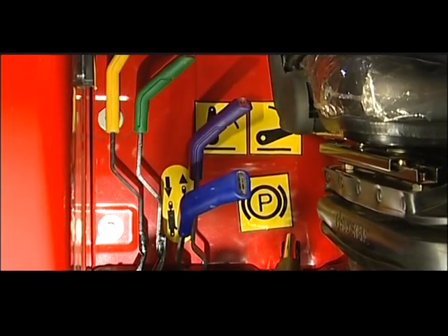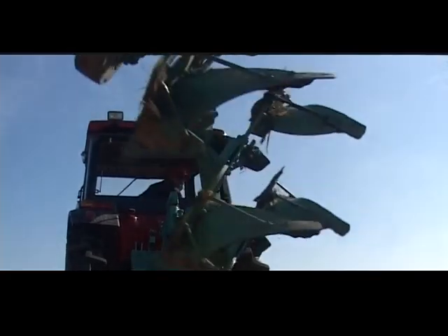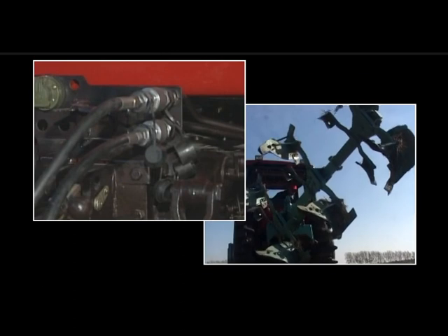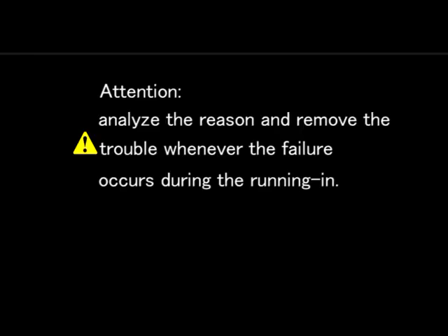Operate each hydraulic output valve lever to up or down positions. Observe if the hydraulic quick change adapter and piping system has oil leakage or not. Attention! Analyze the reason and remove the trouble whenever the failure occurs during the running in.